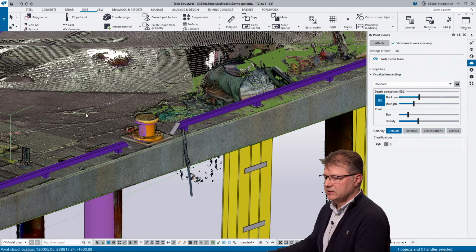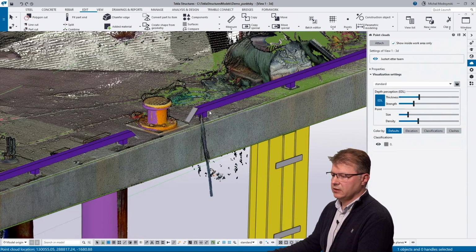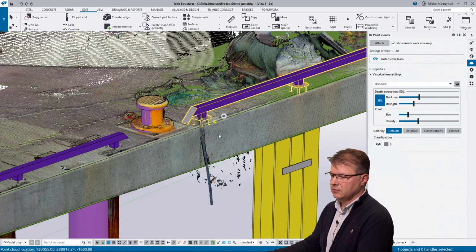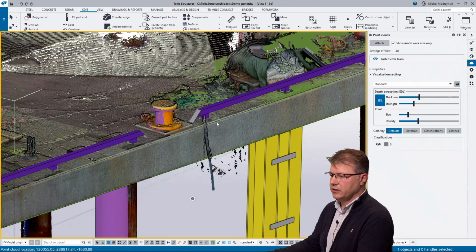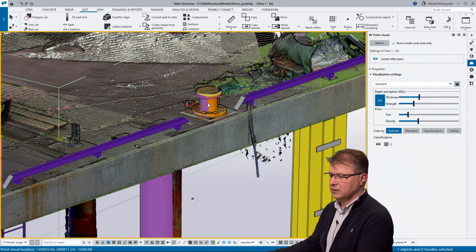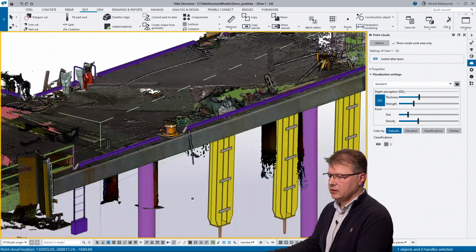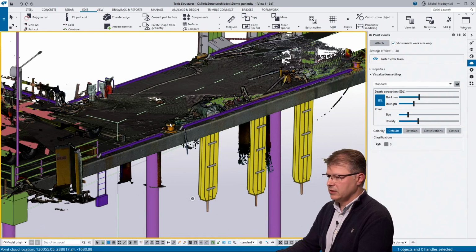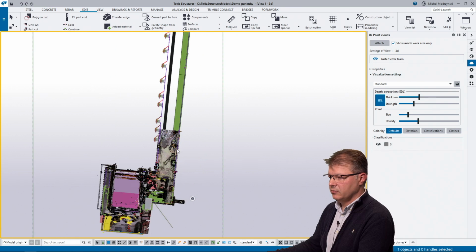Let us just take a look at this area. Here I can see right away, just like a visual check, that those parts are not in the point cloud. So I can see that those are not mounted at all, so I can create a report that those things are missing. For the other things, I can quickly create a work area that will minimize the point cloud.